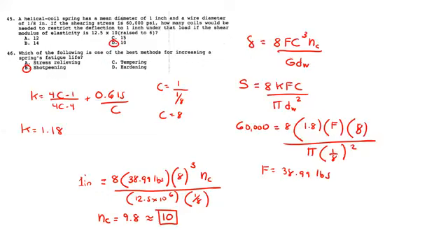Then 47, so ito, a simply supported steel beam, length of L equal to 18 inches and diameter of 1 inch is transversely loaded at its midpoint. So calculate the alternating stress component at the midpoint of the beam in PSI if a constant bending load of 2,000 pounds is applied to the beam, but its location continuously changes from the midpoint of the beam to about 1/3 of its length based on the left end of the beam for each cycle of load variation.